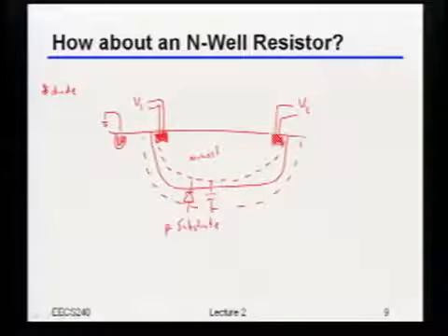I kind of agree with that, but let's maybe ask it a different way. So if I built a resistance, what kind of impedance was I trying to get? High or low? High. Yeah, I want a high impedance, right? Well, if I have a capacitor, then at high frequencies, I'm not going to have high impedance anymore, right? So that's why fundamentally, if I have a resistor and I get a capacitor, that's kind of bad news, right?